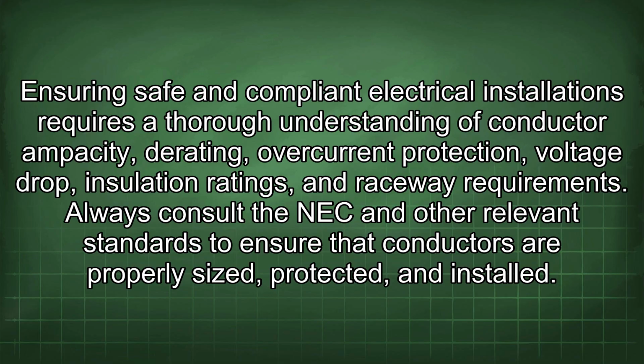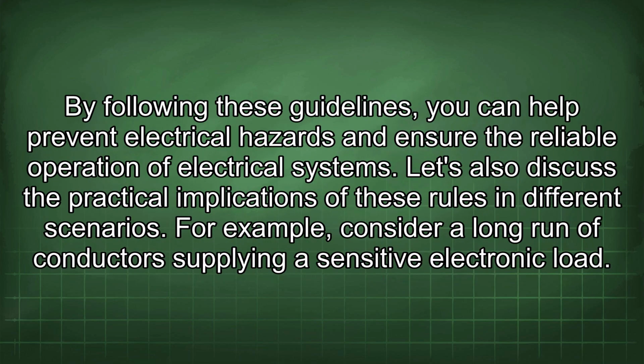Ensuring safe and compliant electrical installations requires a thorough understanding of conductor ampacity, derating, overcurrent protection, voltage drop, insulation ratings, and raceway requirements. Always consult the NEC and other relevant standards to ensure that conductors are properly sized, protected, and installed. By following these guidelines, you can help prevent electrical hazards and ensure the reliable operation of electrical systems.